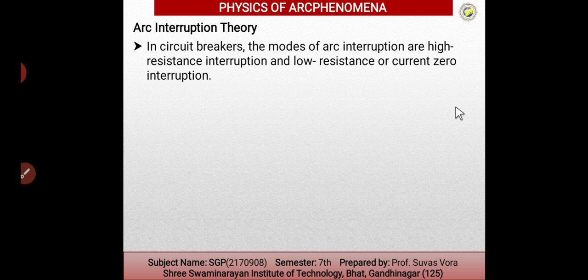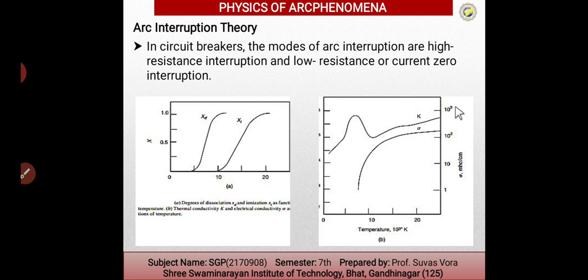During the circuit breaker breaking the contacts, the arc occurs between the contacts due to the high currents flowing. The arc consists of a column of ionized gas, and the electrons, which have a negative charge, are attracted towards the positive contact and, being light, move towards it very rapidly. You can see the figure of the electrical conductivity at various temperatures of air at atmospheric pressure.